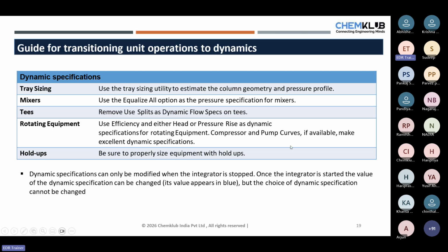Compressor and pump curves are very important because a vessel is defined by its dimensions, while rotating equipment is defined by the compressor curves or the pump curves. So it will give you the true representation of what is happening, or how the system will perform for those rotating equipment. Be sure to properly size equipment with holdups.